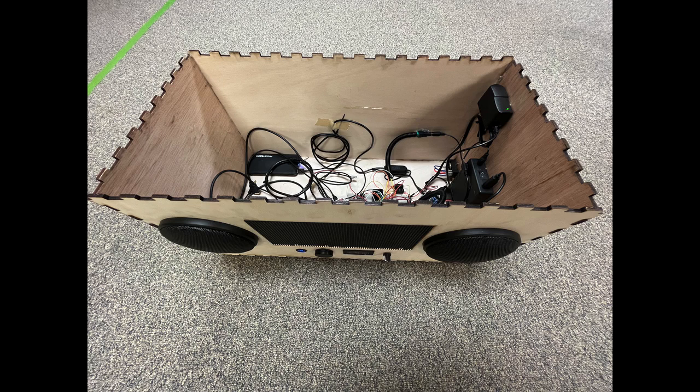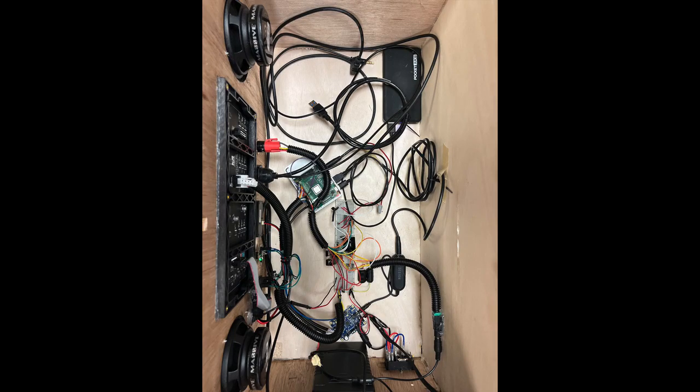In addition to this 12-volt source, we have the 5-volt source, which is connected to both our Raspberry Pi and any peripherals that might connect into the Raspberry Pi. This includes an I2C enabled rotary encoder, which allows us to change the volume digitally as opposed to using an analog method, which would require a potentiometer. In addition to this, we also have a matrix hat, which supplies both power to the LED matrix as well as decodes output signal from the Raspberry Pi and sends that to the LED matrix so that we might be able to display anything that we might prefer.